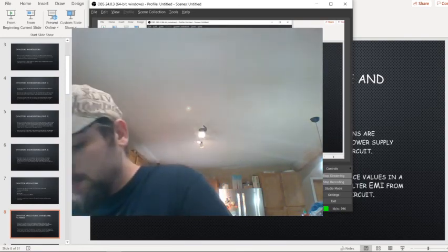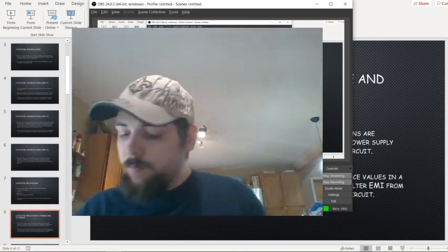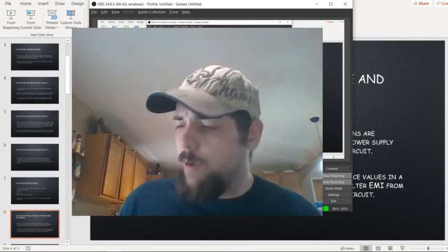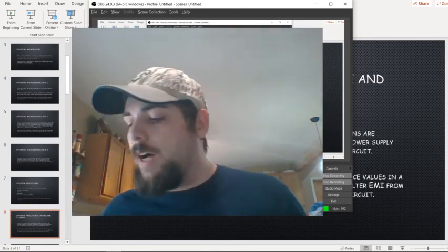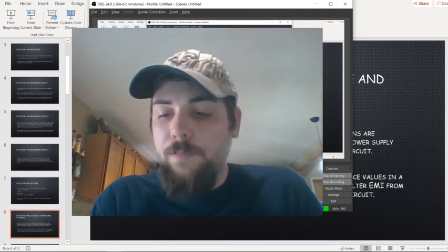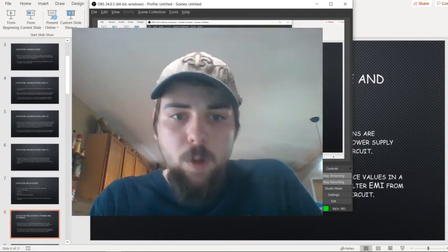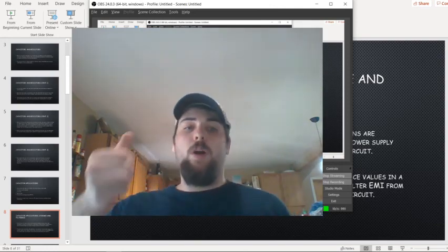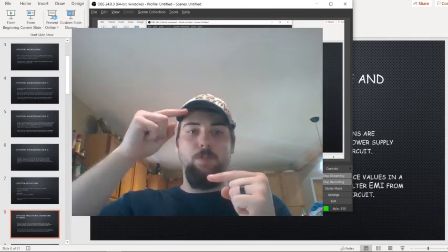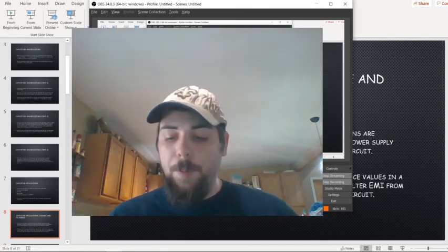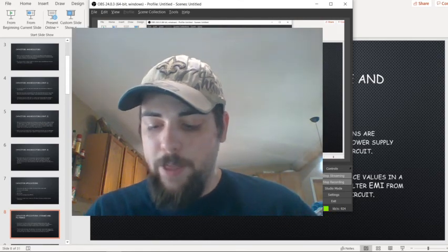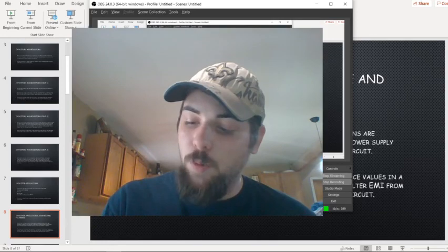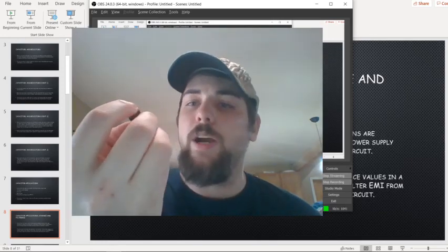Generally speaking, they are a distinctive color like this blue, or a weird yellow color that I don't have one handy, but they are rated X1, X2, X3, Y1, Y2, Y3, depending on the application they're used for. So one goes from line to line, and one goes from line to ground. So using the proper ones there is a very important thing. And you'll notice that this is also a plastic shell. This one is also a plastic shell. This one actually has the writing on the top.